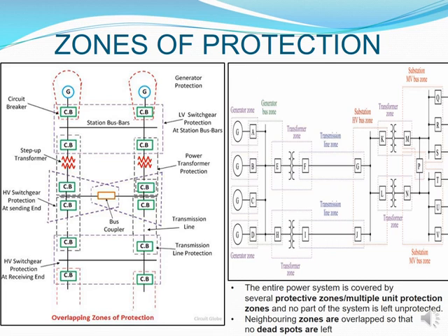In this type of system, you just have too many networks that are involved. It would have been easier to do what we learned in graded overcurrent systems if it was just a one generator system. One generator, then you would have had a radial system in there. But because it's two generators, you've got an interconnection from one side to the other in case one of your generators goes out. So that is why it becomes a little bit difficult to use the graded system over here. So we need to use unit systems in it.